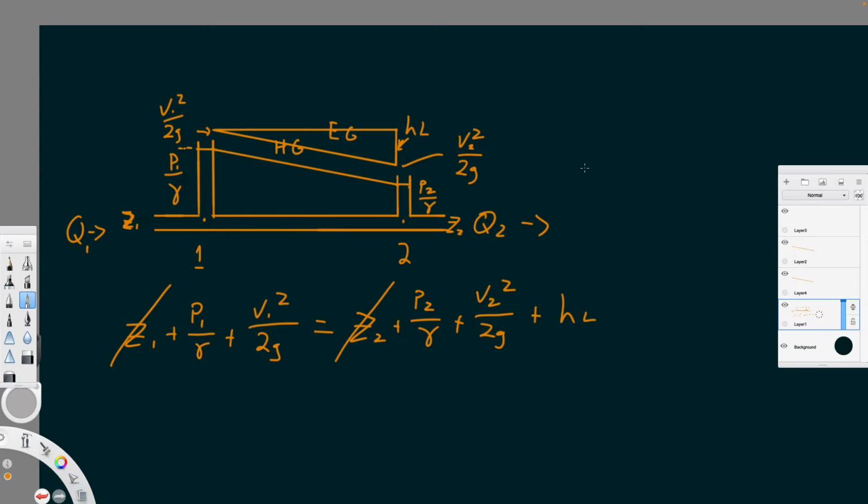Okay, so hopefully you remember that the flow rate at point 1 is definitely going to be equal to the flow rate at point 2, right? Because we're going to assume that the pipe is rigid, so it's not going to swell up and store more volume. And what's important about fluids when we talk about fluid mechanics? An ideal fluid is incompressible. We always consider them to be incompressible, which means it's not being compressed, so it's not storing any volume in that way either. So you're always going to have the same flow rate.